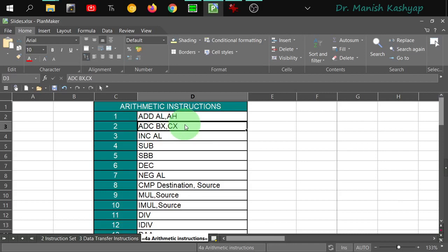So these are simple instructions. I am not elaborating anything on that. After that, we have this increment instruction. So increment will simply increment the value of the register by one, right? The only point to note here is that we can use a memory location or a register of either 8 bits or 16 bits. And if a register of 16 bits has a value of FFFF, and if you try to further increment it, it will become all zeros. So that should also be kept in mind, right? So again, these are circular in nature.